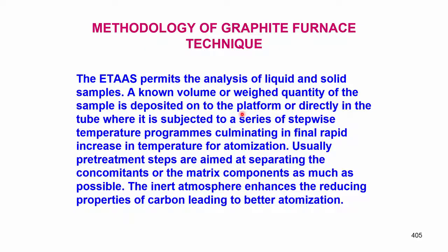Both methods are available in the market. Platform is better, and if you do not have a platform, you can deposit on the tube itself, and then it is subjected to a series of stepwise temperature programs. That means heat it to 90 degrees, remove water, heat it to 120 degrees, remove some organic solvents,